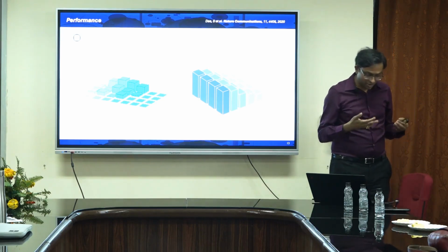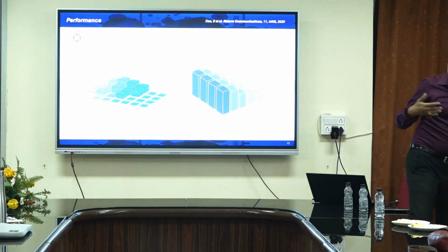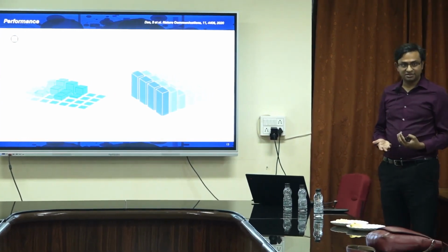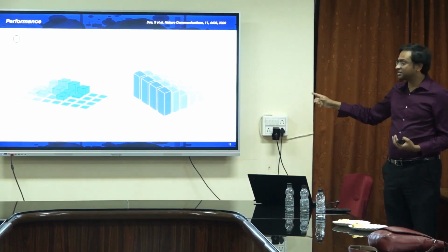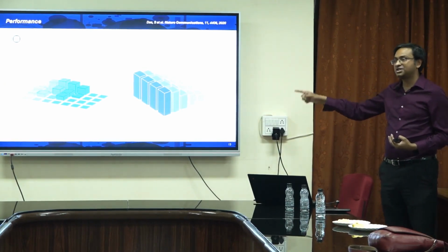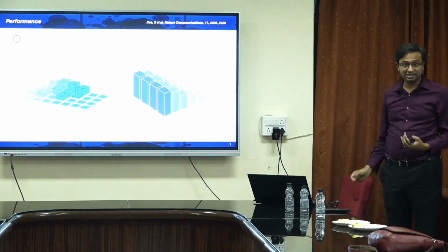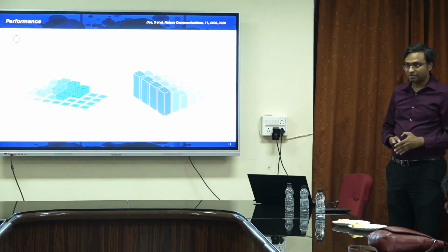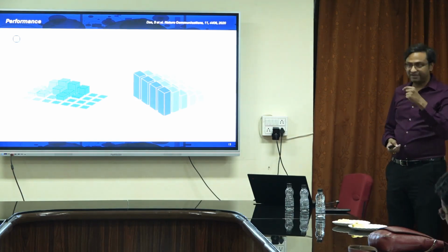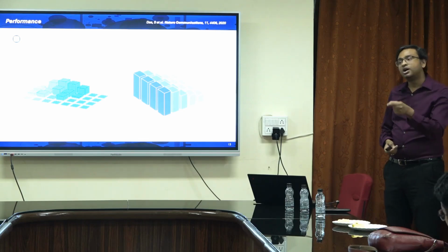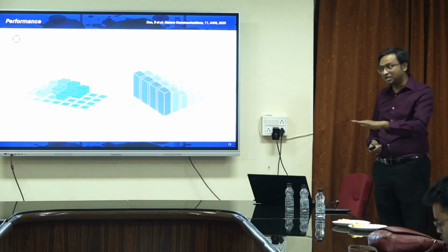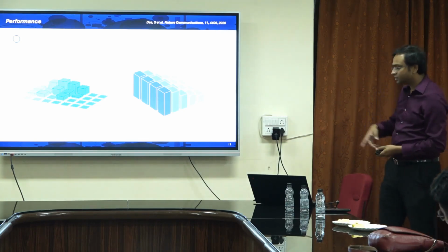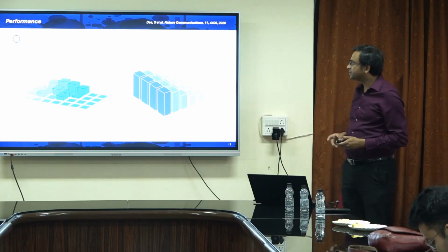Because at the end of the day, we are doing biomimicry. So if we replace the silicon photodiode, we have to be better in terms of energy efficiency. So 2D material based phototransistors give me better energy efficiency even compared with the commercially available silicon photodiode, right? Because I have the third terminal, which is not available for the silicon photodiode. Makes sense? So more flexibility as well as lower power consumption, and that's the common theme for our entire discussion, right? We are trying to get to low power devices. This part is clear? Makes sense?